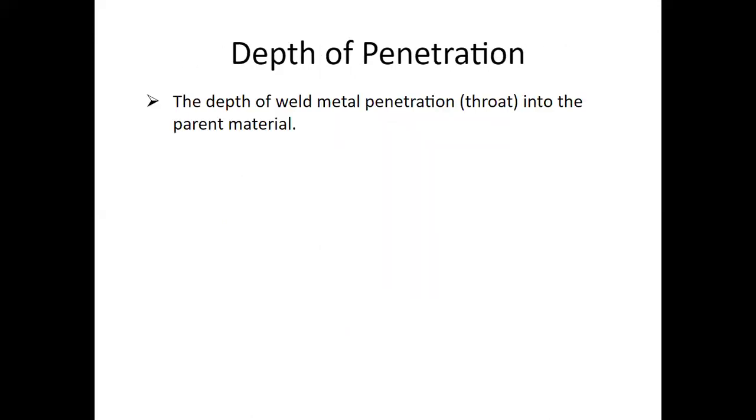So depth of penetration is basically something you don't often see on weld drawings. I've never really seen it, but they have certain expectations that you do get full penetration of the weld. But I don't actually see them measure the penetration of your weld, because to do that would have to be a destructive process. They'd have to somehow get in there and check it out or x-ray it. And if it's very important, they will x-ray it. But honestly, it's a lot of time and money, and a lot of trust is placed in you as a welder to complete the job as per spec.